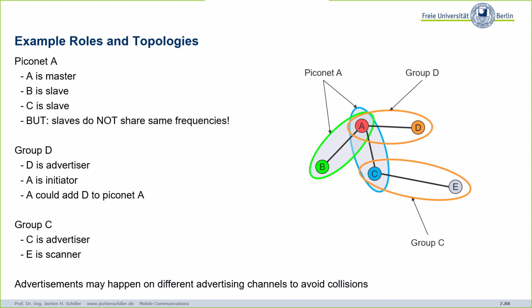Yes, that's okay for a headset, but not for a beacon or for a sensor that you just pass by and it just transmits some data, in a supermarket. You don't want to pair there. You also don't want to pair with the Corona app or something like this. There you just exchange some data, measure the signal strength. That's the idea. So is there an equivalent to services and all the characteristics in classical Bluetooth?